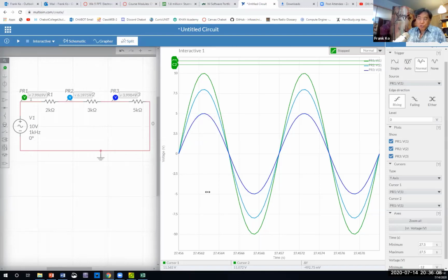So without the cursors, we can still use the division markers to tell us how much voltage these waveforms are displaying. But when you have something like that light blue waveform that's in between 7.5 and 10, it's kind of hard to approximate. We can use a cursor, grab either 1 or 2, doesn't matter. I'm going to lay this one right down on the tippy top of the light blue waveform, and hover right about there. We expected 8 volts, and guess what? We measure 8 volts. Pretty cool.